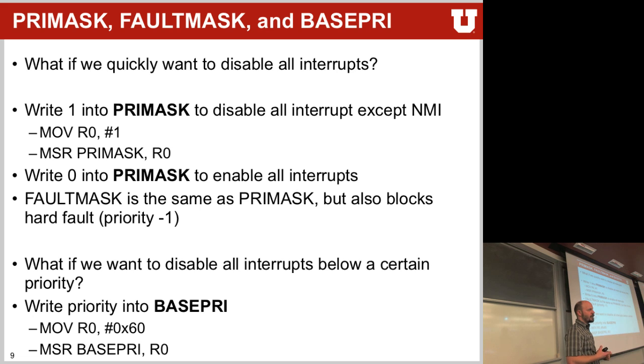That's the only difference. Usually, you don't want to do this unless you really are sure that this is what you want to do. Because then all of a sudden you can do divides by 0 and all kinds of things, and it will just all be turned off. Sometimes that's also what you want to do, because sometimes you cannot guarantee an input, so you want to turn off the hard fault, because else you end up in the hard fault handler. So you can turn it off and do some dangerous code before you jump back.